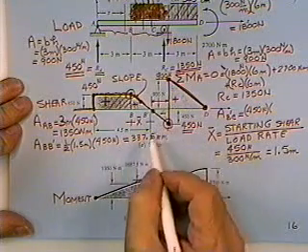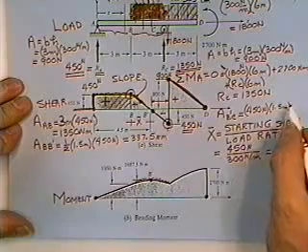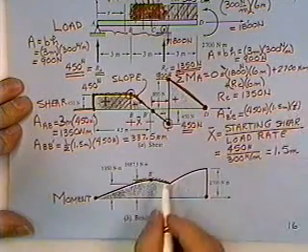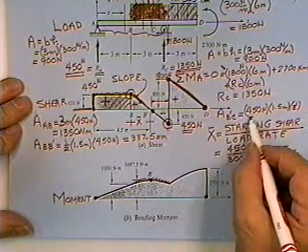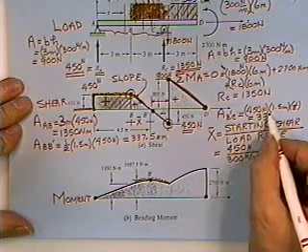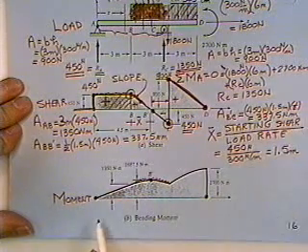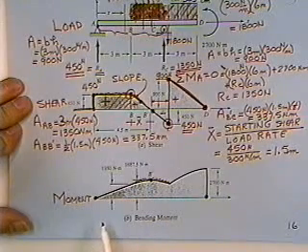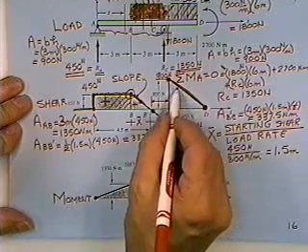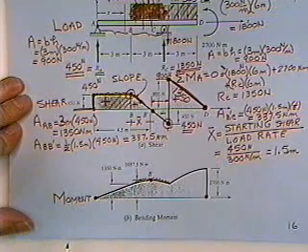I'd simply subtract that from the total length, 1.5 meters. And the area factor of a triangle is 1/2. So that area is equal to another 337.5. And finally, the area of that big old triangle down on the end, 1/2 base height, 1,350 Newton meters worth of area.